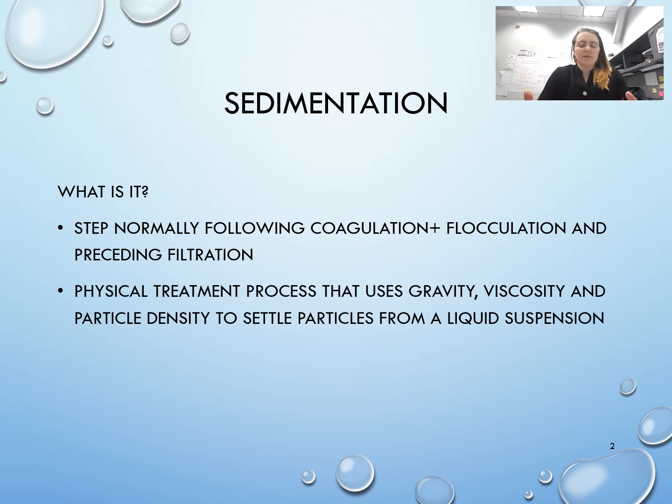It's a step that normally follows coagulation and flocculation, and it's going to precede filtration. It's kind of the backbone of how we remove particles in a system. So it's a physical treatment process. There's no chemicals added. It's not biological in nature. It's going to use principles of gravity, viscosity, and particle density to try and settle particles from a liquid suspension. So you have all these particles floating around in the liquid and they're nice and suspended. We now want to have time for those particles to settle to the bottom of a tank.